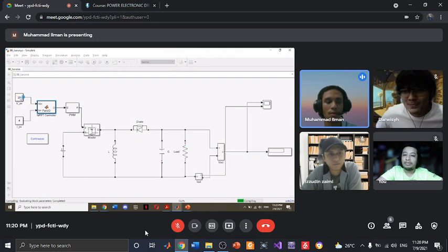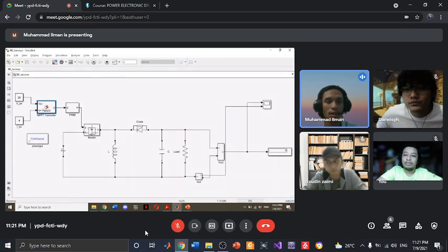its voltage and current can be varied. So the MPPT controller will calculate and set up a specific duty cycle in order to get a regulated voltage. So our regulated voltage is 400 volt. So for the buck boost, the voltage will be negative. So we will get nearly the 400 volt. This one we got 390 volt, negative 390 volt.